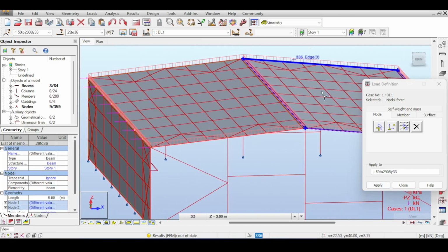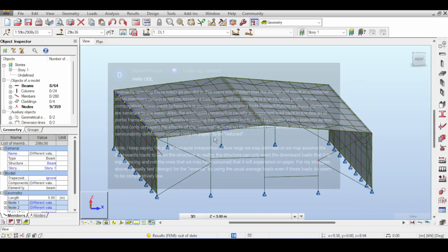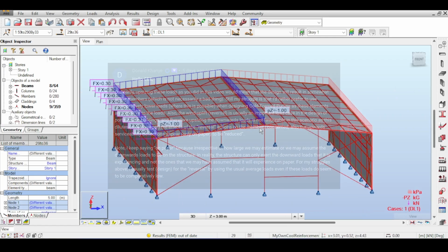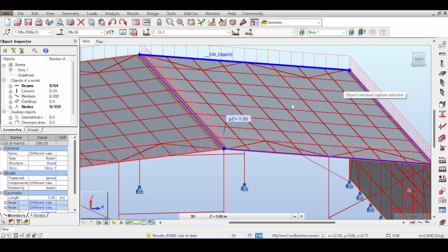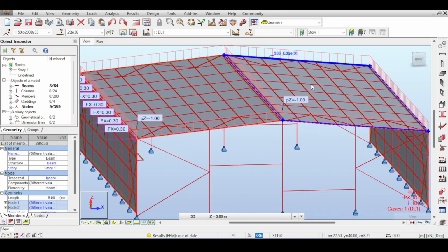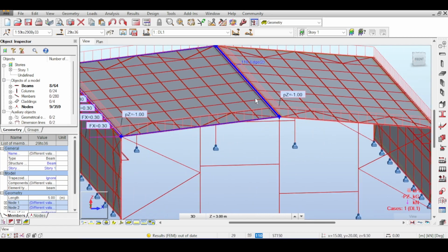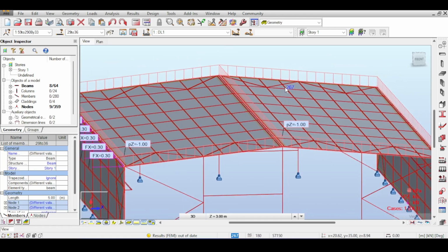Of course, there was a nice discussion between me and engineer Khanye talking about the dead loads, that sometimes oversizing dead loads will affect your purlins negatively when you consider other load cases. An example he gave, and I want to elaborate on that, if I understood him correctly, was about the uplift forces, because remember, in the wind load, there are loads pushing up, and you have combinations where you have uplift forces with dead load, and it helps the stabilization of the structure.